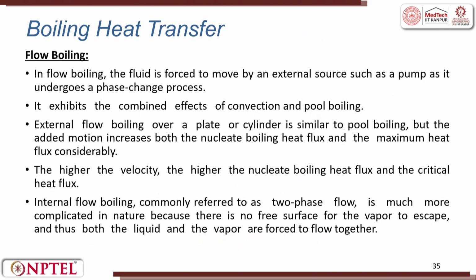Now, when we go to forced boiling or flow boiling, the fluid is forced to move by an external source such as a pump as it undergoes a phase change process. It exhibits a combined effect of convection and pool boiling. External flow boiling over a plate or a cylinder is similar to pool boiling, but the additional motion increases both the nucleation boiling heat flux and the maximum heat flux considerably. So, the higher the velocity, the higher the nucleation boiling. If you keep pumping very fast, the nucleation boiling heat flux will also be very high.